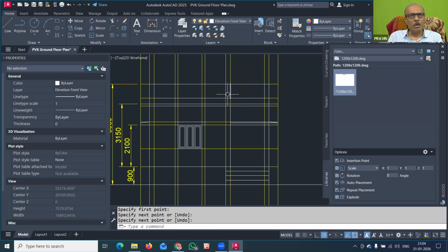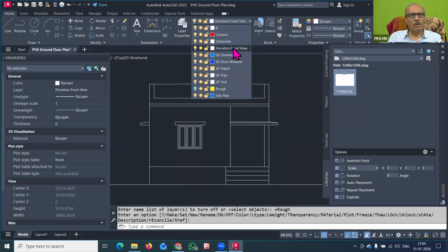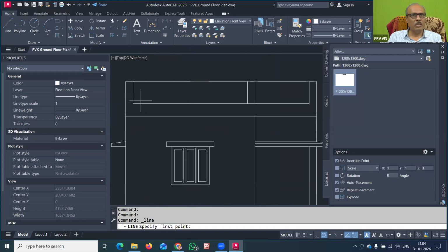Now with this, this is one part of the hall and this is one part of the veranda. So you can again bifurcate this and you can make the center of this also. So there we can also have one dummy column. So I will close again the rough wall. Now with this we can have one dummy column here. So for that we will just take the center of this line again, and I will draw one vertical line from this.